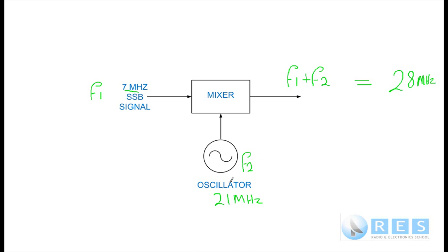If we were to engage the engine quickly, then the engine would stall. Well, oscillators can stall too, but you can't fry potatoes or cook chips with the power coming from an oscillator. They're very, very low power devices in the milliwatt range. For that reason, if we take too much energy from an oscillator, it will cause the oscillator to stop oscillating. So in order to overcome that, we put another stage after every oscillator.